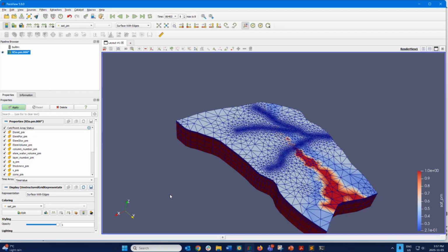If you need to calibrate your model by running it 12 times, you can run that coarse model 12 times easily in a day. Whereas with a refined mesh that might take 10 hours at the baseline to run, well, that calibration process is going to take a lot longer.